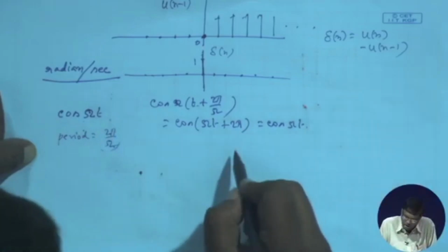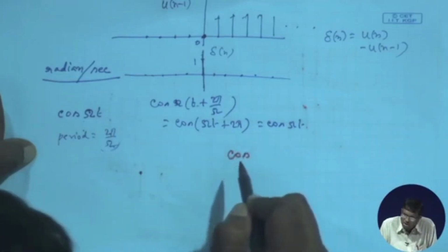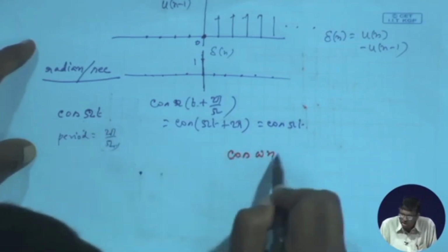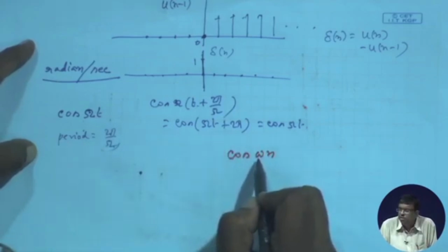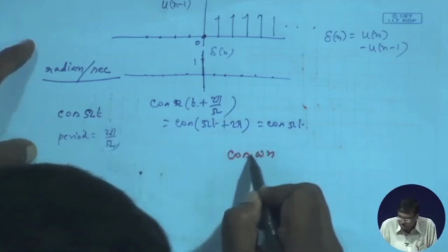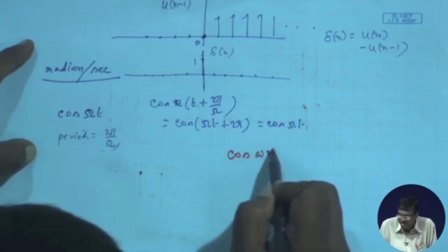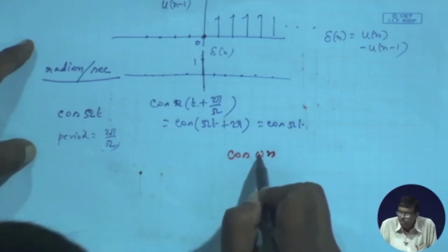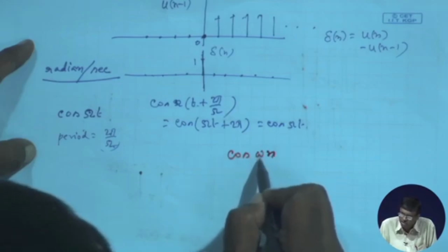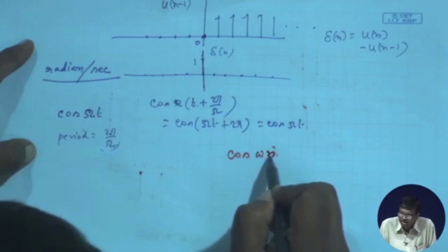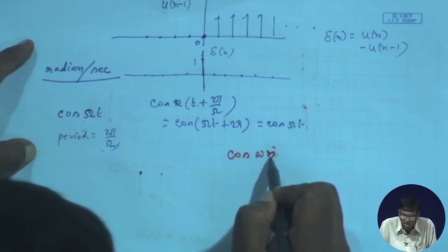But if we construct in an analogous manner some small omega n instead of capital omega, in the digital case we use small omega, and remember again this has to be radian, but there is no time involved in n, it is dimensionless. Therefore, small omega must be just radian, not radian per second, because there is no second involved; n is just a dimensionless integer.